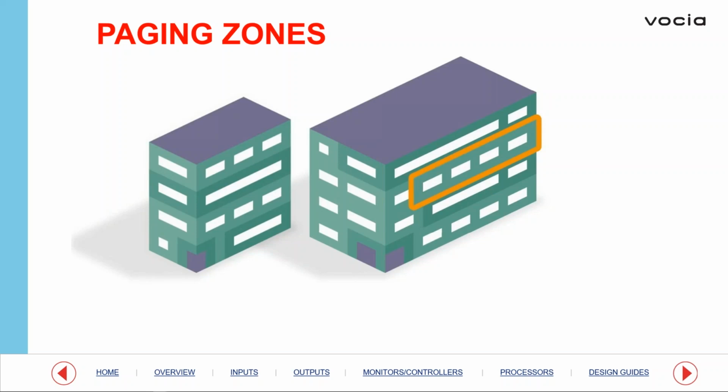So back here, if you look at our diagram, we only had 3 of these areas here that were actually a part of a zone. And then we'll just hypothetically say that there was some kind of advancement, some kind of need, where now all of a sudden it's 4 of these windows or areas. Well, if it was hardwired completely separate, back to its own amplification channel, what could be done is we would use a page code. And that page code then would incorporate both those zones.